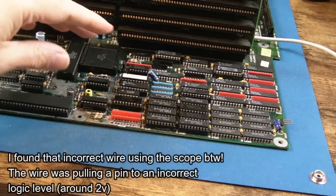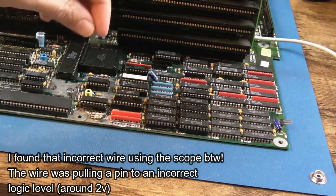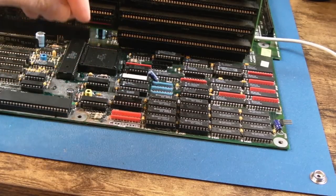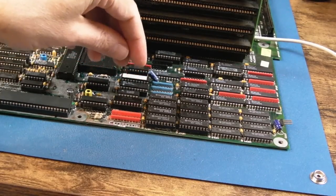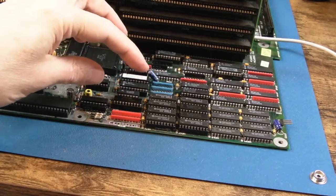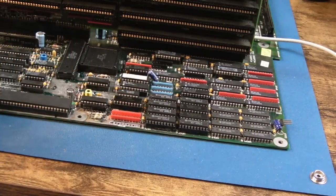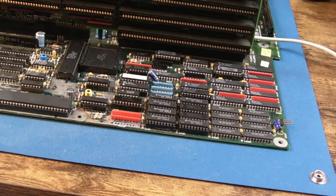So there were a number of things going on, and this is the problem when you've got this level of corrosion. You can very easily lose track of what you're doing as you're going around fixing things. You've got to be really thorough, meticulous, and slow, and double, quadruple check everything. Do you know what I mean? Check everything a number of times before you commit to soldering a chip on, including making sure all the traces are good all around that whole area, and that you've not mistakenly connected something where you shouldn't have done to try and fix a connection.